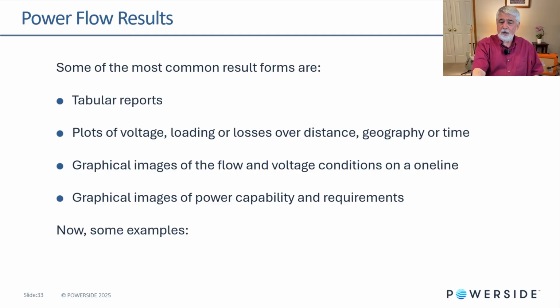Plots of voltage and loading over distance or geography. That's important for distribution feeders. Graphical images of flows on the one-line diagram, so you get that electrical connection perspective. And then finally, this last one, graphical images of power flow capability and requirements. I'll show you that one, which requires a Python program.